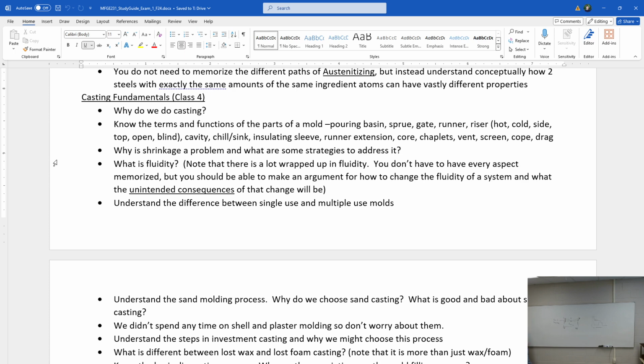So you use little pieces of metal to support it at the right place within the mold until you get the material in there. The chaplets all get melted out, but by the time they do, you have metal all around the thing. Then your problem is that the core wants to float because it's lighter than all the metal. So the problem has reversed, but anyway, that's fine.